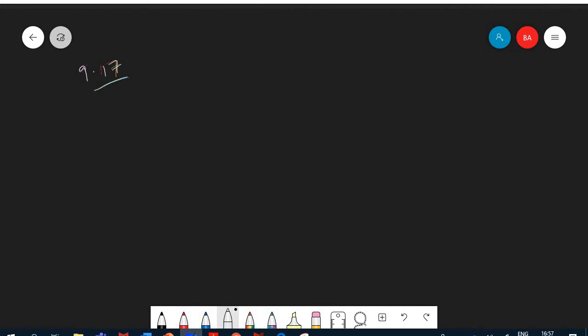So in 9.17, in part A, we had a vessel here, and because I have only relief of vapors, I have my rupture disc, and then I have my spring one as well. And of course, in this case, this is what we need to do. Then you're going to send it to flare or to the scrubber.